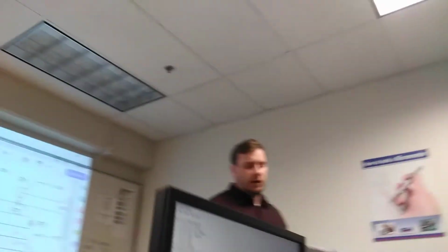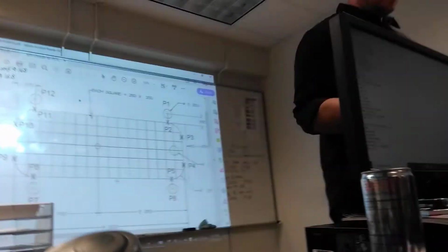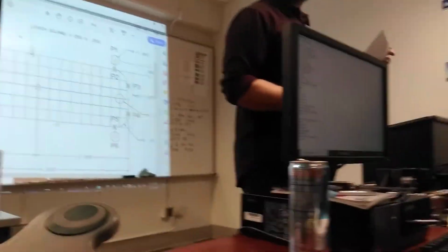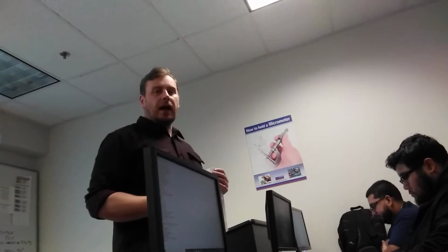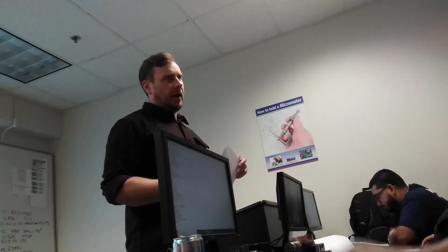It says cutter compensation can be simplified if you have a basic understanding of manual machinery. There are 2 common types of cutting conditions. What are they? Climb and conventional. What kind of cutting are we supposed to do on the CNC? Climb. There is no backlash to worry about. Always try to climb cut.